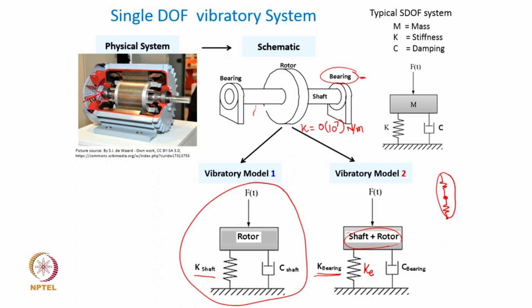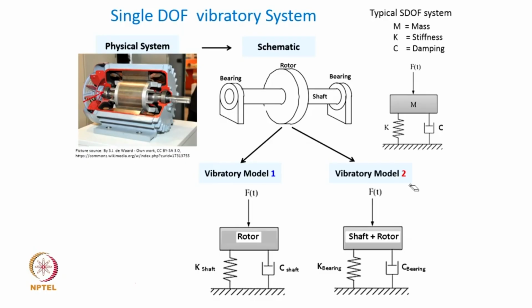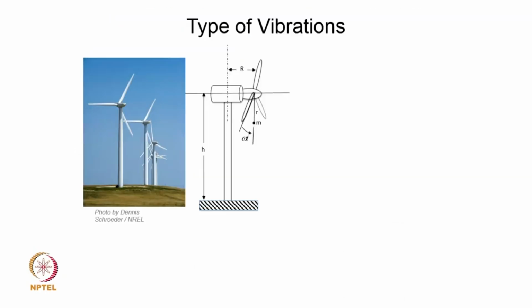Now, in addition to this discussion, I would like to also discuss a little about what kind of vibration analysis that we can perform, or in the sense of types of vibrations or the modes of vibration, right. So, the example that we have been discussing of a wind turbine nacelle sitting on the column like this, we have seen that there will be a bending moment acting on it, there will be a twisting moment acting around the axis of the column, and then as this bladed rotor rotates, there would be a fluctuating vertical force which is going to act axially, and longitudinal excitation will excite the column.